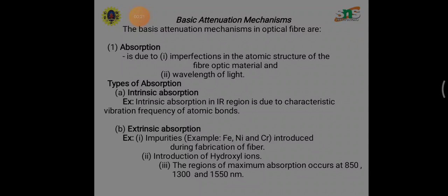So losses can be divided into intrinsic and extrinsic loss types, depending on whether the losses are caused by the intrinsic fiber characteristics or operating conditions. Intrinsic optical fiber losses consist of absorption loss, dispersion loss, and scattering loss caused by structural defects or the quality of the optical fiber core itself. Extrinsic optical fiber losses originate from splicing loss, connector loss, and bending loss.